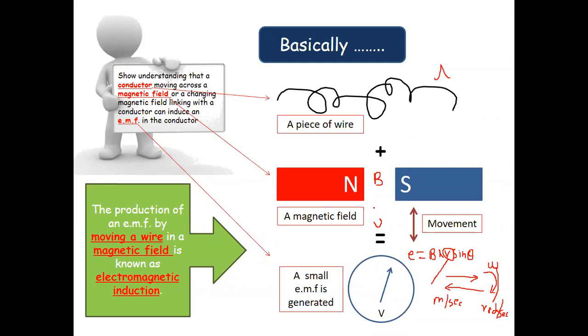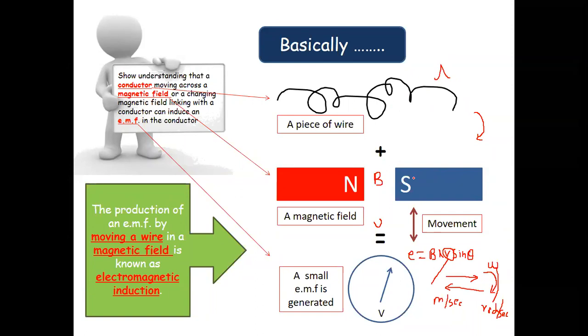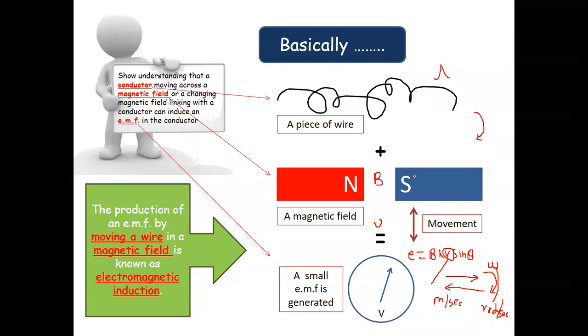If the conductor is moving with an angular velocity of omega radians per second under a magnetic field of B, then it is going to cut the magnetic lines of force, and EMF will be induced in it. Faraday's law says that the magnitude of EMF is directly proportional to the rate of change of flux linkages.